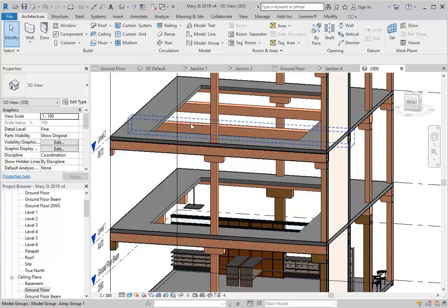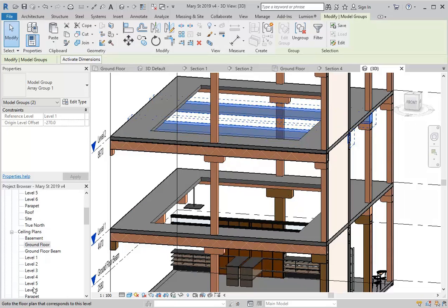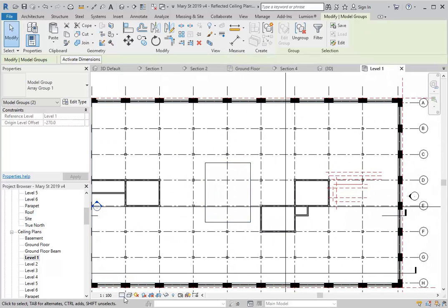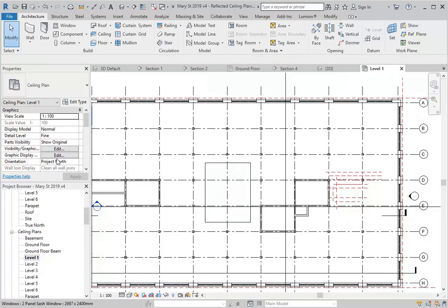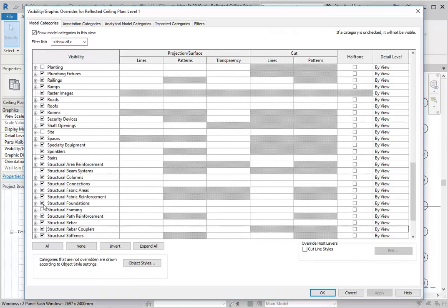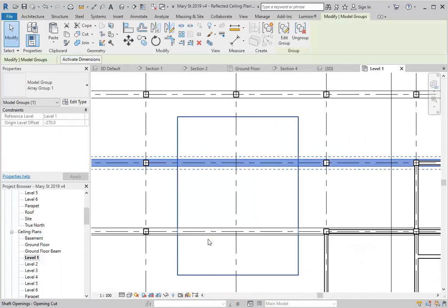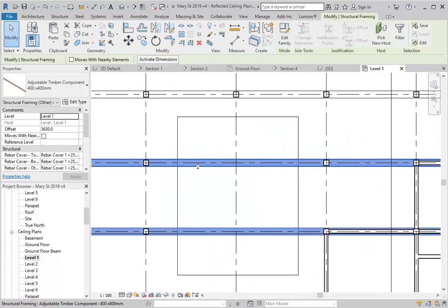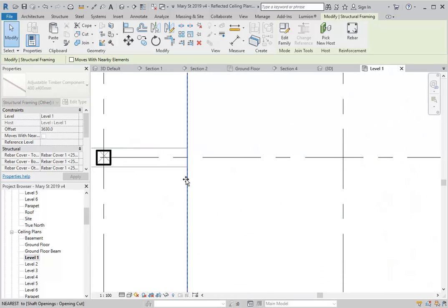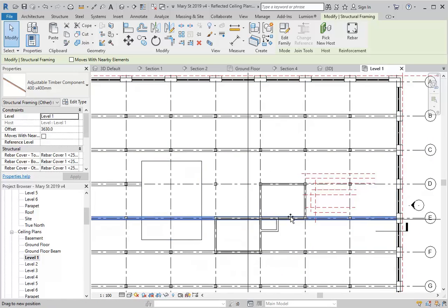So I'd need to do the same on the next level, with these two beams. You mirror the next one. You could copy them, but mirror is a bit easier, I think, because mine will have the different side. Mirror or copy, they both would work. It's up to you. Then just remember, you need to do that on each level where you have a shaft. And in a way it's good that you're forced to make the building the way it's going to be built, because then you can treat this as a design exercise and think of nice ways of detailing that.